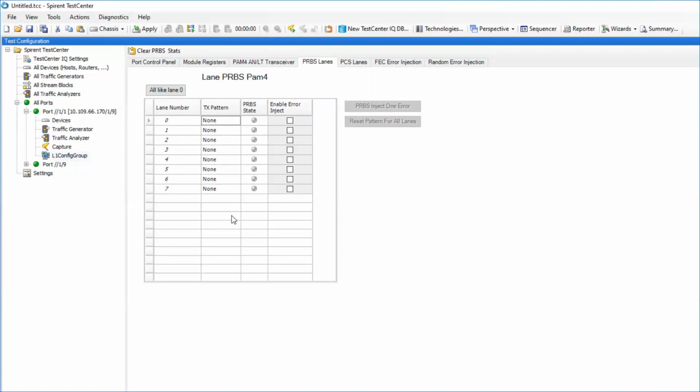The PRBS detection engine is active only when link recovery is disabled. If the receiving port doesn't detect PRBS on a given lane, Spirent Test Center reports none for the pattern detection and increments the total seconds of no PRBS pattern received result. It may take up to 10 seconds to detect PRBS on all lanes.